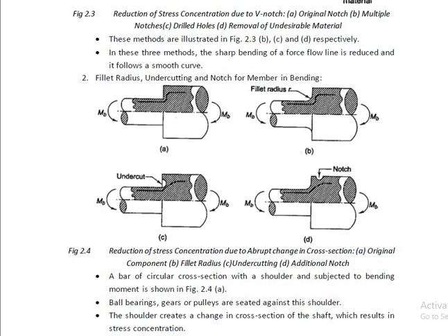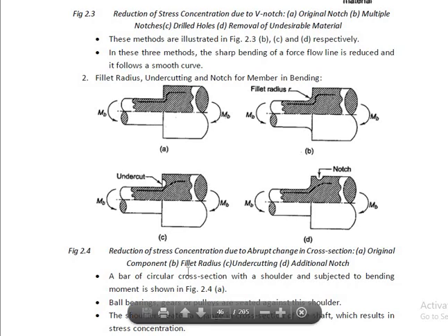Look at this streamline, this is the force line. It is suddenly changing its direction, so there is a possibility of stress concentration at this point. Now how can we reduce this stress concentration? The first method is the fillet radius.